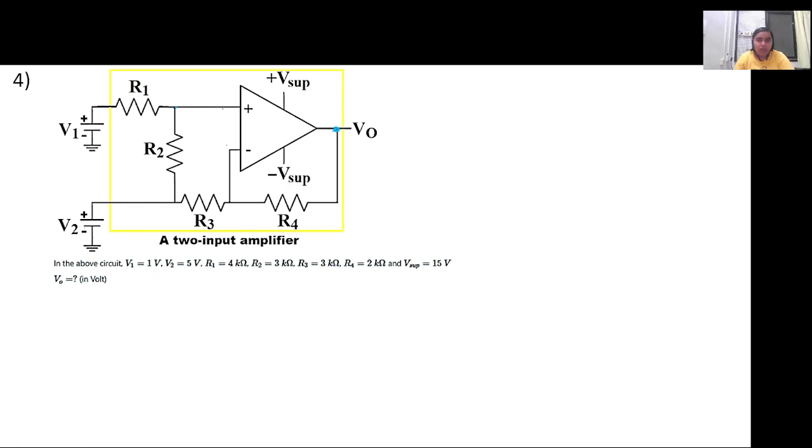So one thing that we know here is whatever the voltage here VA will be equal to the voltage here VB, VA equal to VB, and there is no current getting drawn in here, right? So I'll just write this node voltage as VA, and this node voltage, since it is connected to VB and VB equal to VA, I will also write as VA, right?